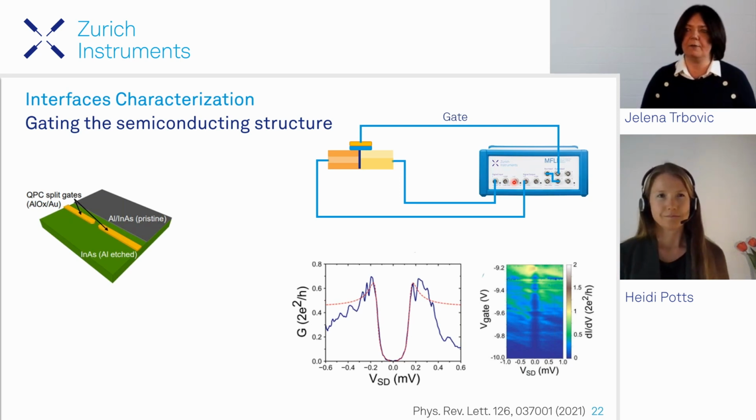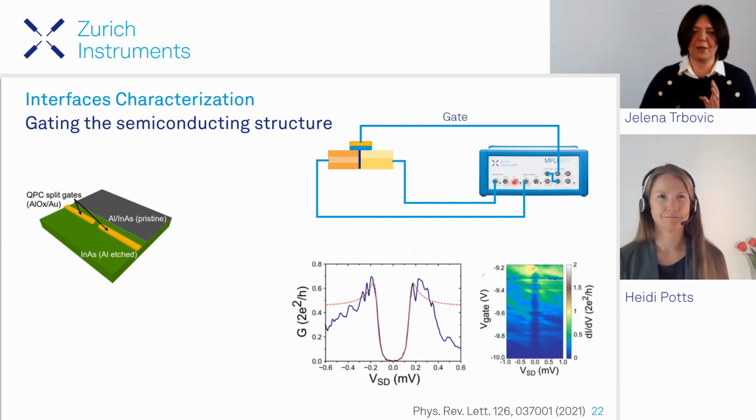Let's say to have definitely, if you want a rule of thumb, maybe 10 times you divide your frequency by 10. So for example, if you measure at 100 hertz, you can have maximum 10 hertz bandwidth. And lower, of course, you need to be careful not to pick up the 2 omega component, and maybe in that case you will have much more noise.